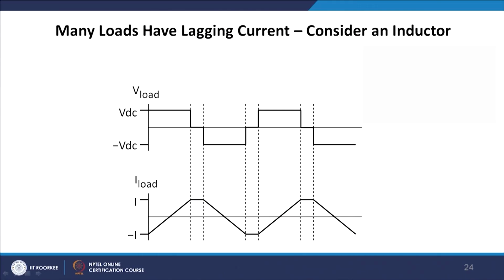Now, this is your load characteristics. So, we can see that if we consider a lagging load, a highly inductive load, then in this case current will lag if we apply DC voltage VDC, or VAB. So, ultimately current will ramp up. Thereafter, when you apply 0 voltage, current will be flattened. So, current will flow through the diode in that region.